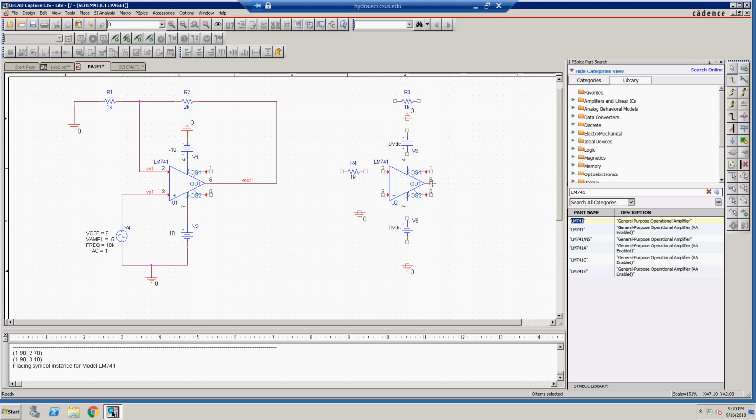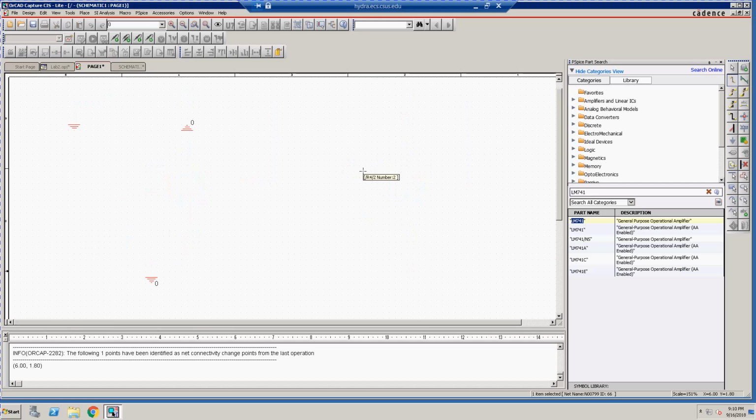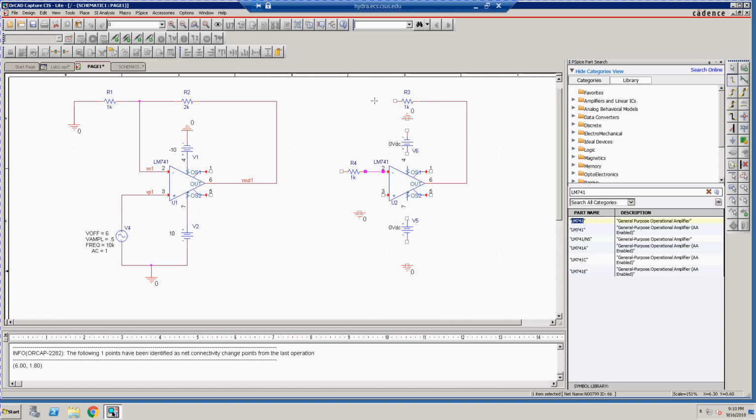Now one click ties it to a point. So I'm going to click on the output. Then I can come out, and if I want to do a 90-degree turn, I click again. I can come up, click again, draw over, then terminate on the resistor node with the final click. Same thing, we'll connect the rest of these up here, come across. And we're going to come down to connect our feedback resistor. We have our supplies. Okay, connect this to the op amp.